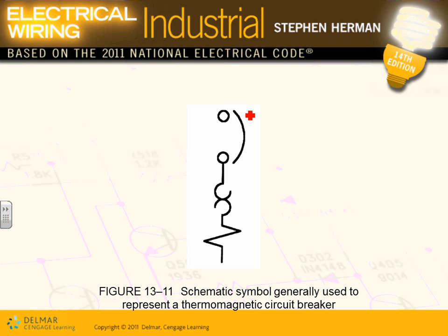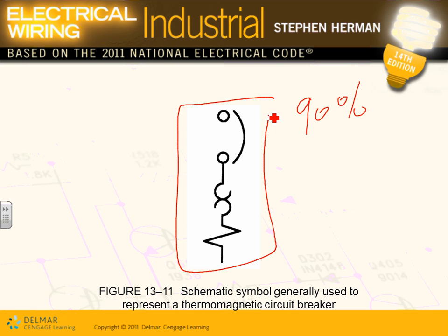They use a different application. Now, Karen, 90% of the time, guys, I want to put 90% of the time, your circuit breaker will have dual components. This is called the thermal and magnetic, thermomagnetic circuit breaker. Can I have thumbs up, Chad? We know why thermomagnetic. It has a coil that trips on short circuit and a resistor that heats bimetallic material.